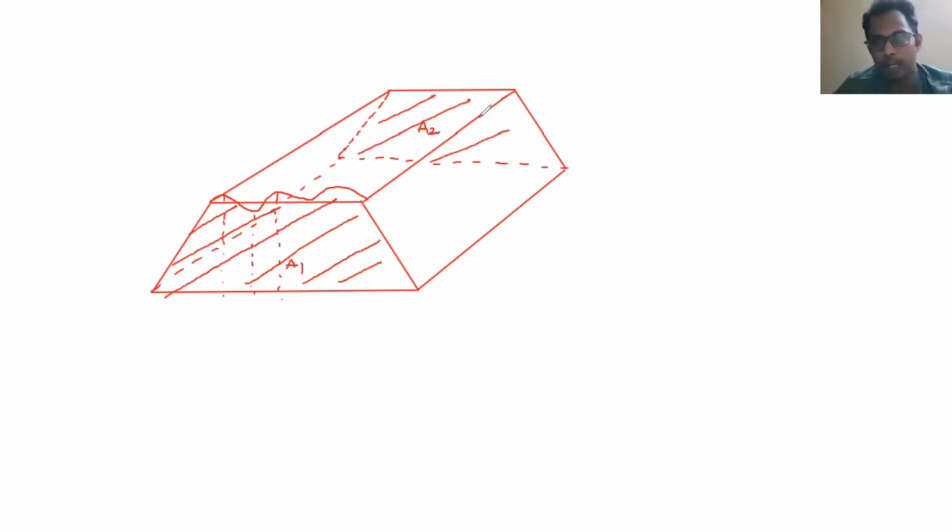For finding the quantity here, measuring length, width and depth is not possible for me. So what we do generally is take the average of areas A1 and A2, multiplied by the length. Sometimes you can take the quantity using length, width and depth; sometimes it may not be possible. In those locations, we use different methodologies for getting the quantities.